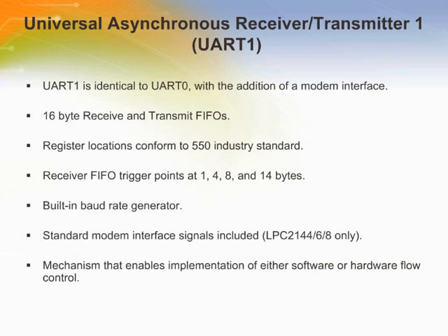The UART1 baud rate generator block, U1BRG, generates the timing enables used by the UART1 TX block. The U1BRG clock input source is the VPB block, PCLK. The main clock is divided down per the divisor specified in the U1DLL and U1DLM registers. This divided down clock is a 16 times over sample clock, NBAUD-OUT. The modem interface contains registers U1MCR and U1MSR.